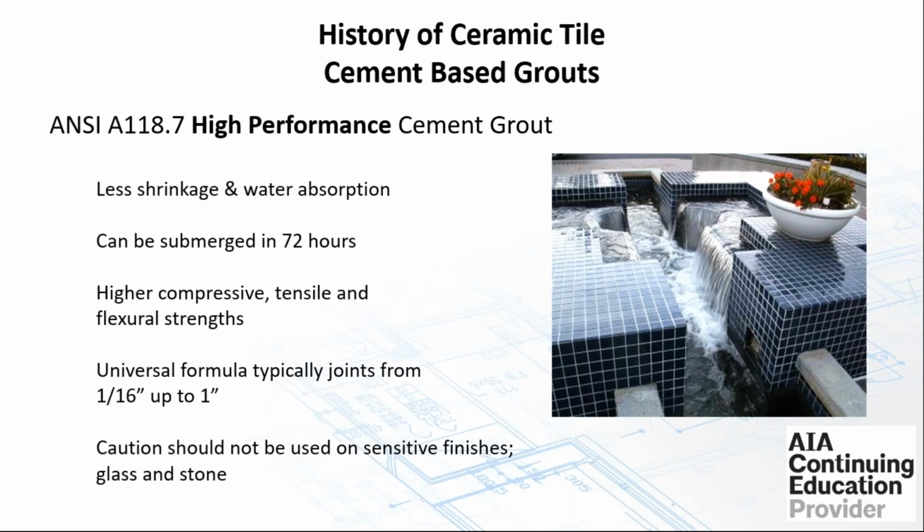It does have less shrinkage and less water absorption. One of the advantages of this grout is that if you're in a project where you need to get it submerged into water, within 72 hours we can submerge this grout and it's cured out to where there won't be a problem with it. So this is a great application for exterior use where inclement weather could be coming in. If we can keep that covered for 72 hours, rain and such won't affect that grout.